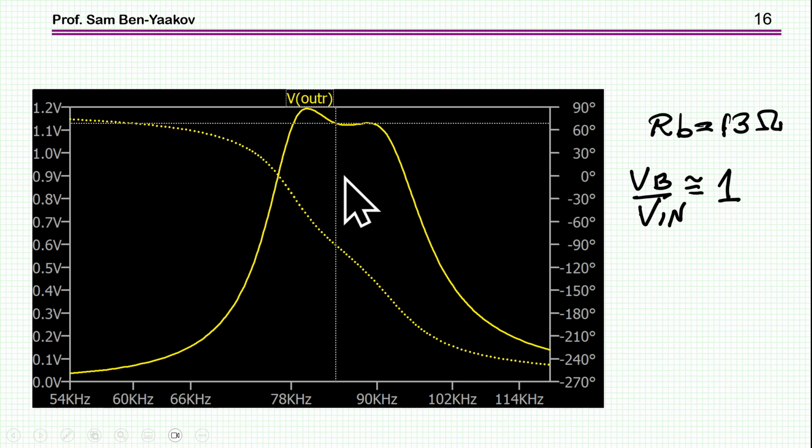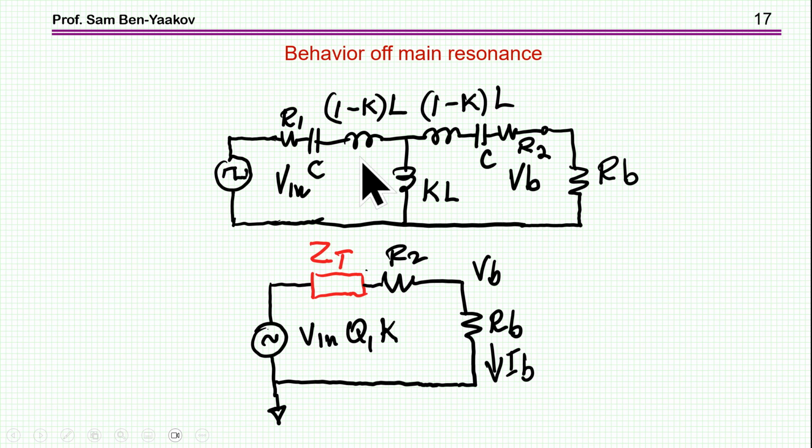Okay? Now let's have a look at this extra resonant point from another point of view, which may clarify it a little bit better for those who are a little bit baffled by this. I've shown this circuit and I explained that if the impedance here is low, let's say short, you can have a resonance between this capacitor and some of the inductances here, and at another frequency, another resonance with this capacitor and the rest of the circuit.